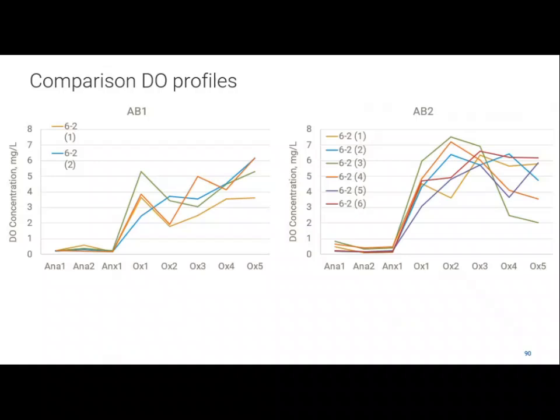Okay, so when you go out and stick a DO sensor into the anaerobic zone and it measures 0.1, don't overreact. You're probably getting to the limit of measurement accuracy of that sensor, right? So it's like, oh, okay, there's a little bit, but that's probably just sensor error. And then when you get to the oxic zone, they're in that 3 to 4 range, okay? And then it's very high DO in the rest of the basin. It got up quickly. With these designs, they needed to be able to get their DOs up very rapidly.